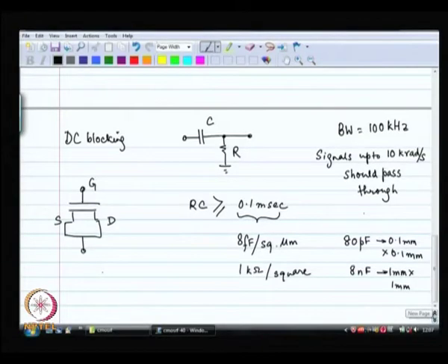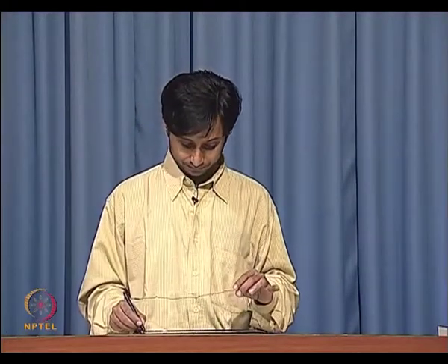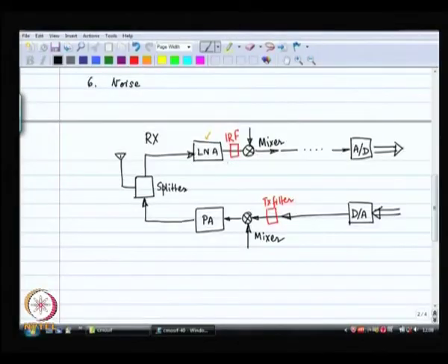So, basically the thought is, do not make direct down conversion receivers when the bandwidth is less. When the bandwidth is more, when the bandwidth is 2 megahertz, 20 times this, the requirement as far as the high pass filter cutoff goes down, and then you go for a direct down conversion receiver. Okay. So, all this we talked about to explain why I need this image reject filter in the receive path.